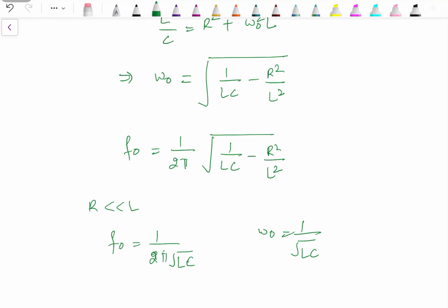And in fact, the expression for resonant frequency in case of parallel circuits depends upon how many elements are connected in one branch, whether we have only a resistive, only a capacitive or only an inductive branch, or a circuit like the one we used over here, or a combination of resistance and capacitance in the second branch. So accordingly the expression for the resonant frequency will change, but the basic concept will remain the same, that is, for resonance the power factor should be unity.